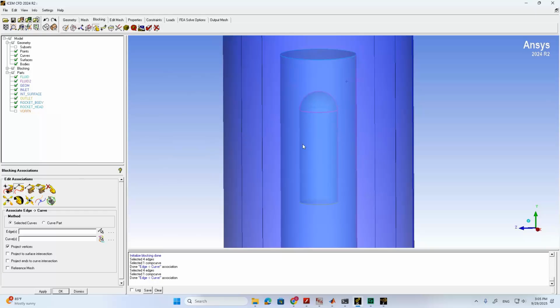If you find this Reynolds number is higher than a certain critical Reynolds number, which typically is 500,000, then the flow becomes turbulent, otherwise it is laminar.